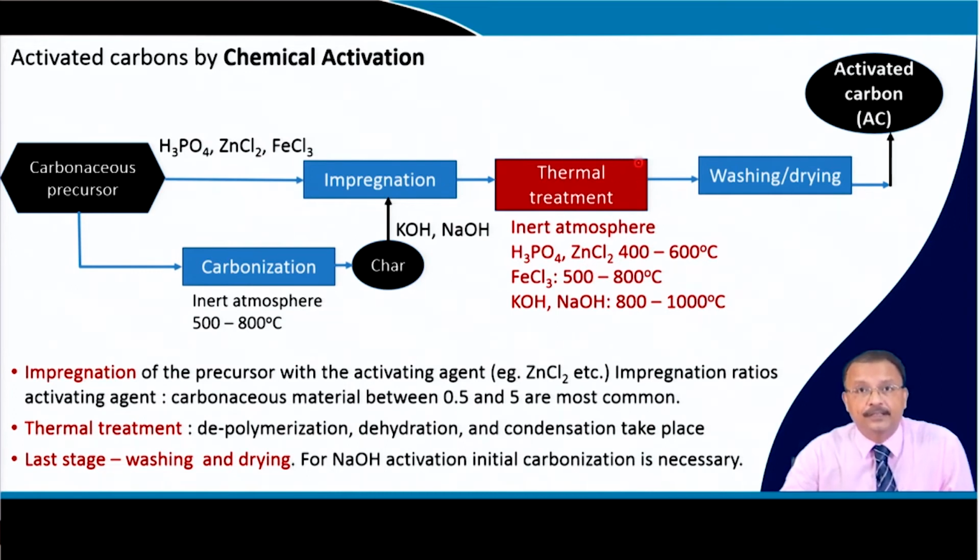And after the thermal treatment, this is washed, particularly when you are using sodium hydroxide for activation. Then you need to wash the material that you have gotten, and that also leads you to the activated carbon. So, in this process, sometimes if you want to do the activation with potassium hydroxide or sodium hydroxide, then it is found that this carbonization is necessary.